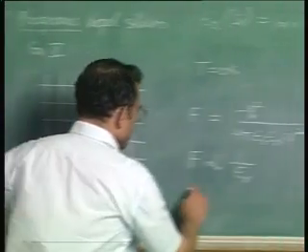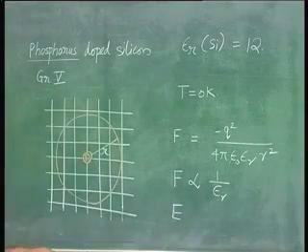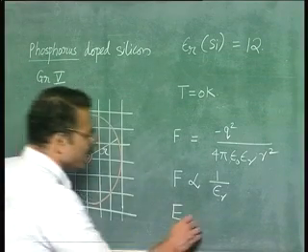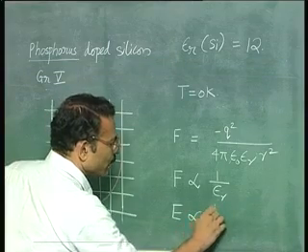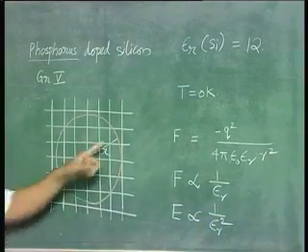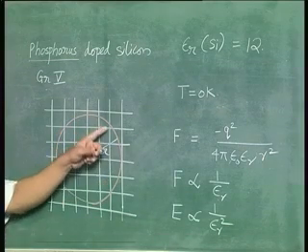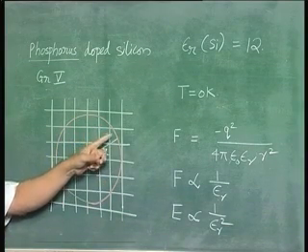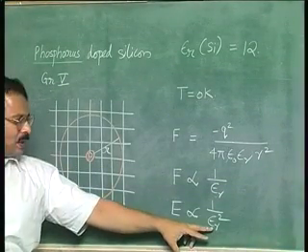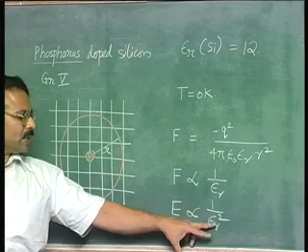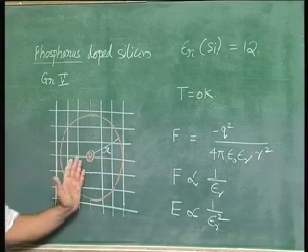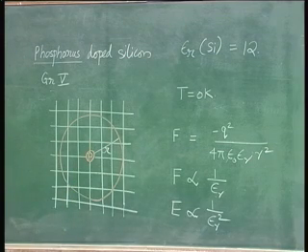If you calculate the energy of the electron in the orbit using the Bohr model of the hydrogen atom, similar to that, you will find the energy is proportional to 1 by epsilon r square. So this means that the energy of this electron orbiting around the phosphorus atom in silicon would be 144 times less, because epsilon r square for silicon would be 12 square, 144 times less than that of a hydrogen atom.